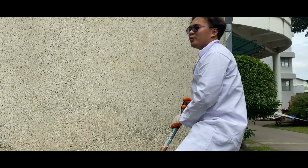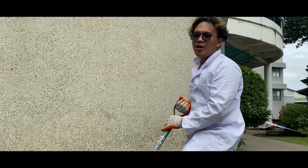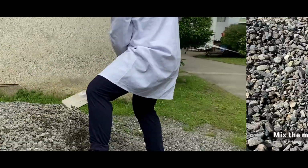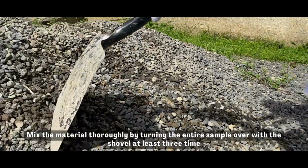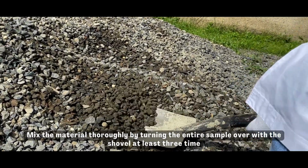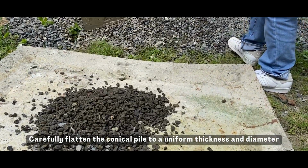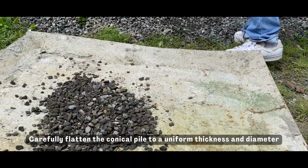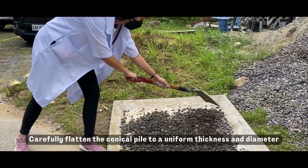So first, we will gather our coarse aggregate samples and put them onto our big tray or a clean, flat, hard surface. Place the original sample on a hard, clean, level surface. Then, mix the material thoroughly by turning the entire sample over with a shovel at least 3 times. Carefully flatten the conical pile to a uniform thickness and diameter by pressing down the apex with the shovel so that each quarter of the resulting pile will contain the material originally in the pile.